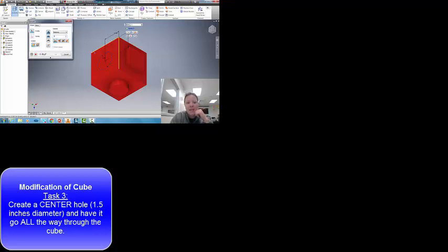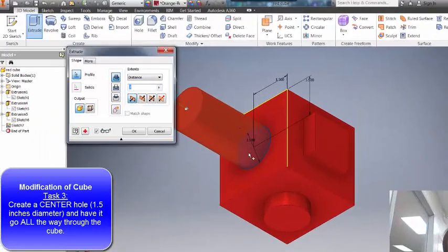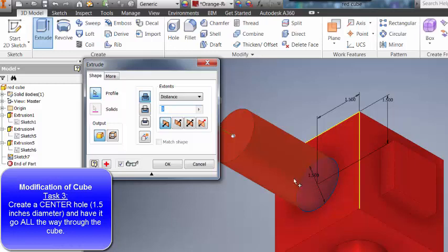So I'm going to type in 3, and I'm going to select the surface that I want to be extruded, which is our circle. So you'll notice I'm hovering over my circle, and it kind of shades it in to let me know I'm on the right surface or the right shape, and I'm going to select it. But notice it extruded out, and I don't want it to extrude out. So right here, right underneath where I typed my 3, you'll see that I actually can change the direction. So if I select direction 2, it actually went the opposite way. It actually went in or through.